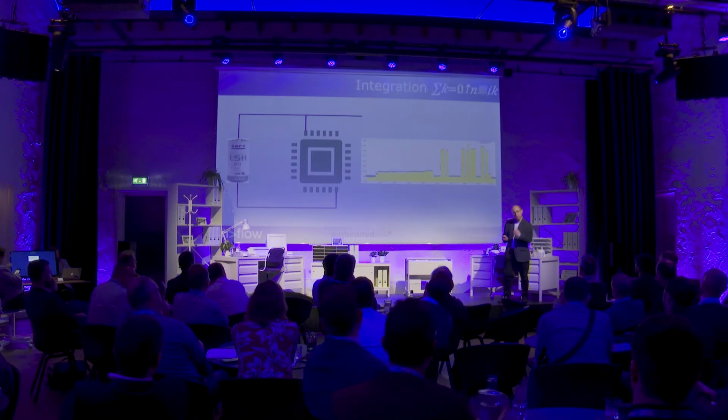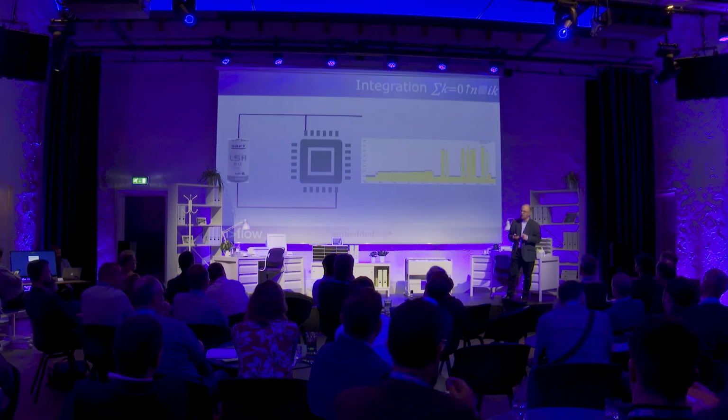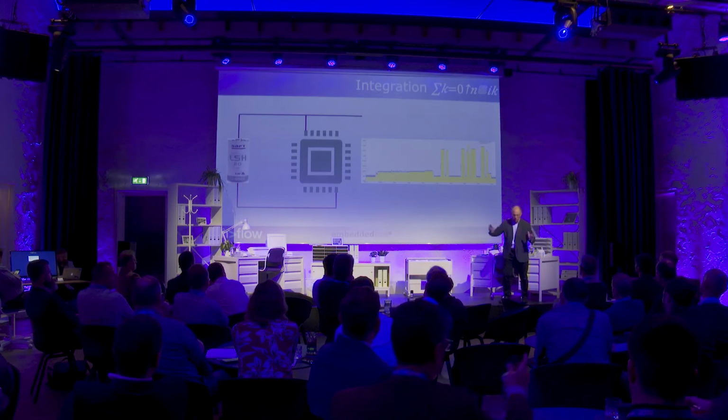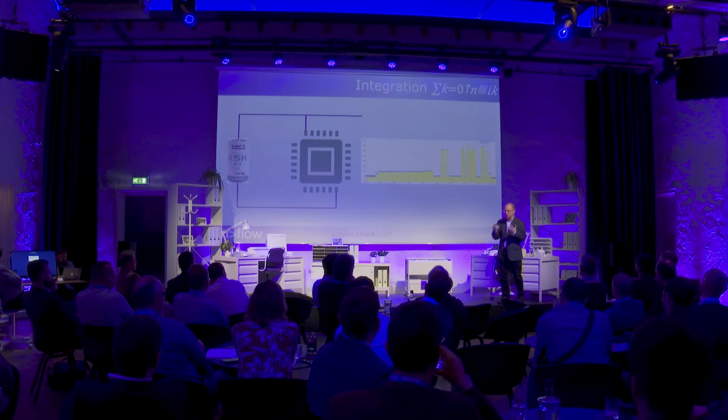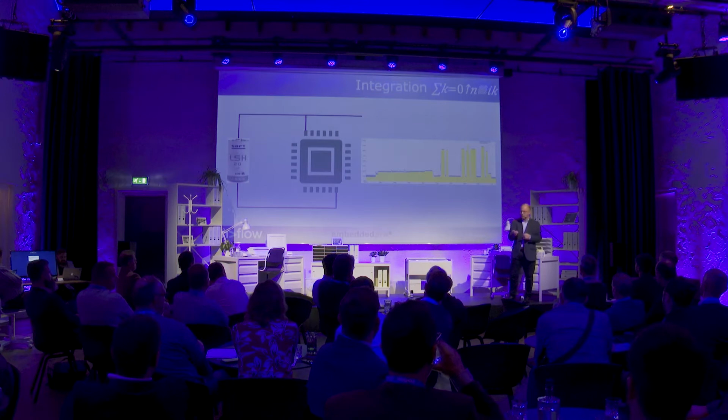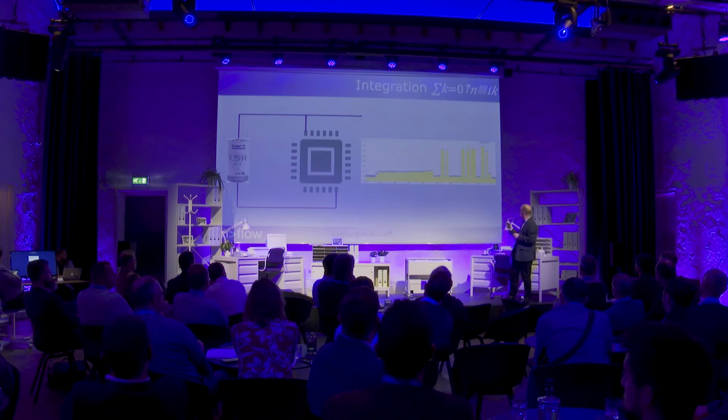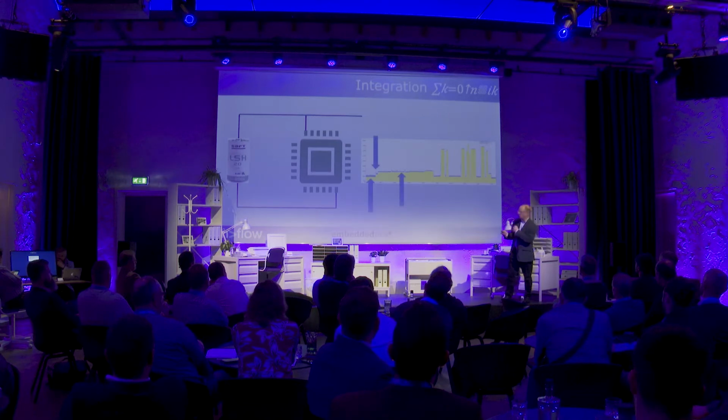So we could just build up the area under this curve by knowing how long in each mode and how much current, and we can calculate the milliampere hours per second or milliampere hours per microsecond. Of course, it's a little bit harder than that because we need to have a reference for these current consumptions. We go to the chip datasheet for that.